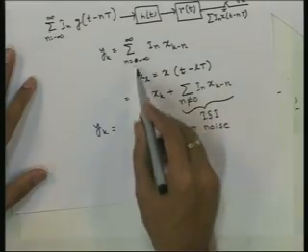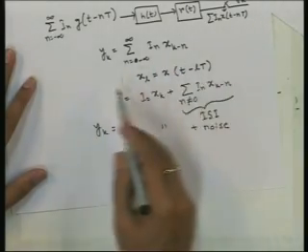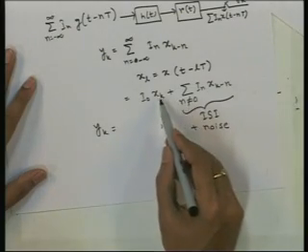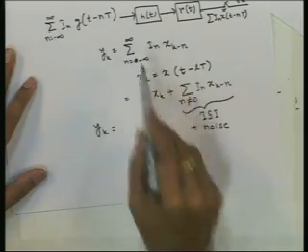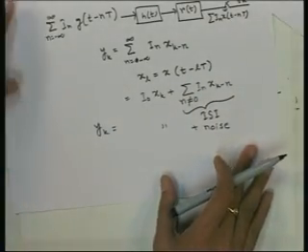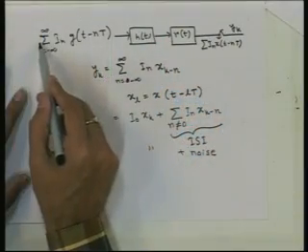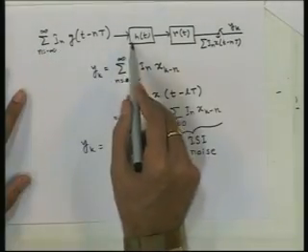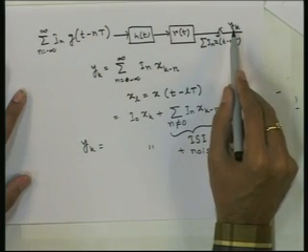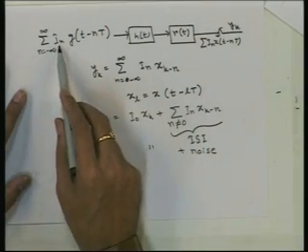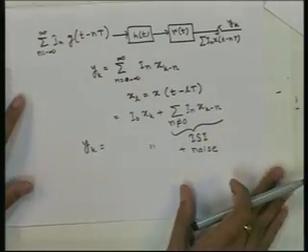And this formula looks as if the discrete time signal x k is going through a filter, and this is the convolution. So, the equivalent model for this whole system, if you consider I n being fed and after modulation it is going through h t, r t and then sampling, then the discrete time signal we are getting here looks like convolution of the sequence I n with some other discrete time filter impulse response.